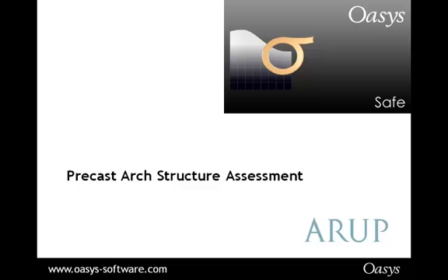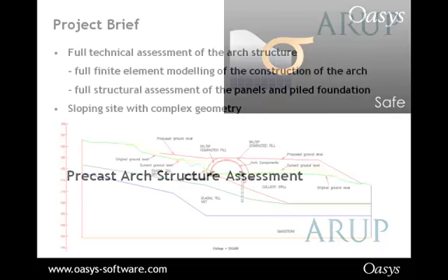They looked at external and internal finite element packages, and SAFE was chosen in this case because SAFE actually deals with 2D plate elements. So you can actually choose the elements to create a line. So instead of, for example, having a beam element where you specify the beam element and that line is where you take the bending moments through, you can choose the elements for the arch and create a line through the arch. And you can choose the bending moment along this line, which is not possible in some finite element packages.